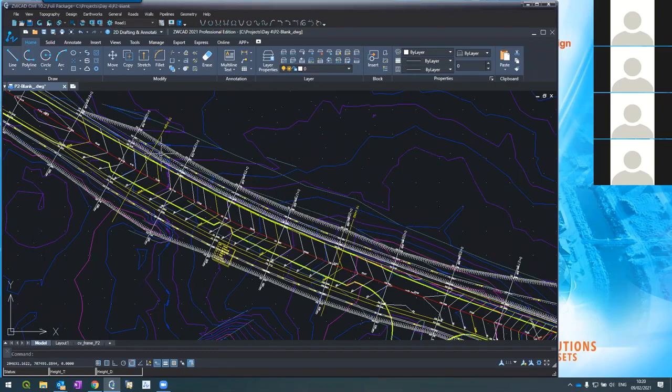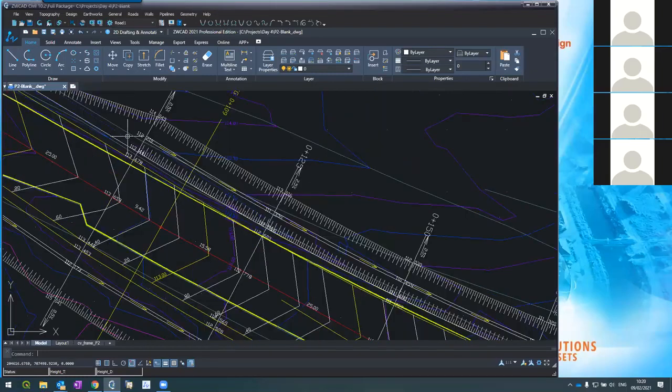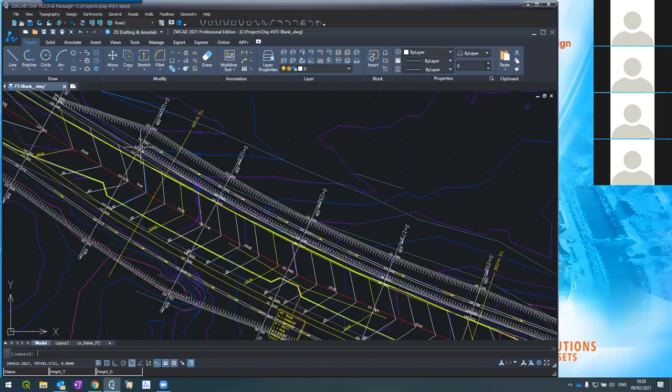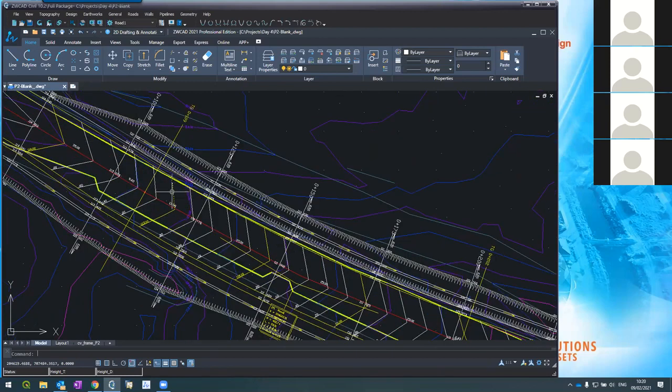Not super elevation, a curve, sorry. A curve. Let's start from here to here. This is the first tangent point, and this is the second tangent point. In this case, we didn't create any spiral, any clothoid, or any transition area in the geometry. Therefore, we will have to create our own transition. I will take a transition, it's my decision, 20 meters. I will start the transition 20 meters before the tangent point and end up 20 meters after the tangent point. This is my decision.